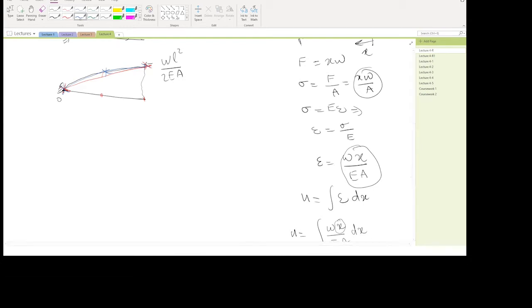However, if you look into the stresses or the strains, the relation between the strain and the displacement is just going to be the derivative. And the strain is the derivative of u with respect to x. You already have an expression for the strain, and this is exactly the same expression you have for the stress, just multiplied by the elasticity modulus.